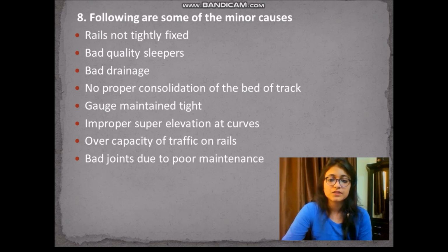Rails are not tightly fixed, bad quality of sleepers, bad drainage, no proper consolidation of bed of track, gauge maintained tight, improper super elevation at curves, over capacity of traffic on rails, bad joints due to poor maintenance. So these are some of the minor reasons.